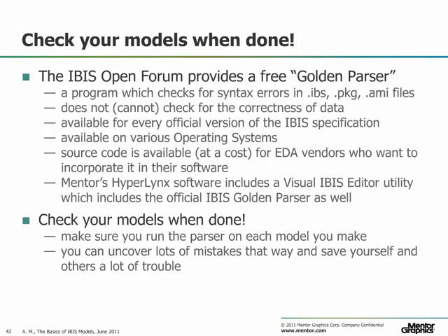A very important step in your model making process is to check your models when you are done. The IBIS Open Forum provides a free golden parser program which checks for syntax errors in your IBIS files. The golden parser, however, cannot check for the correctness of your data. For this reason, you should always run some simulations when you are done with your models to make sure that the waveforms are correct. The source code of the golden parser is also available at a cost for those who wish to implement it in their software products.